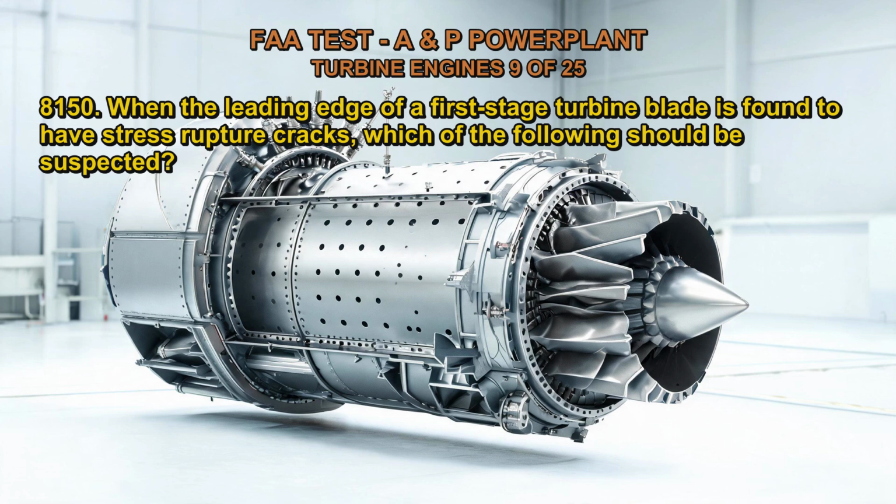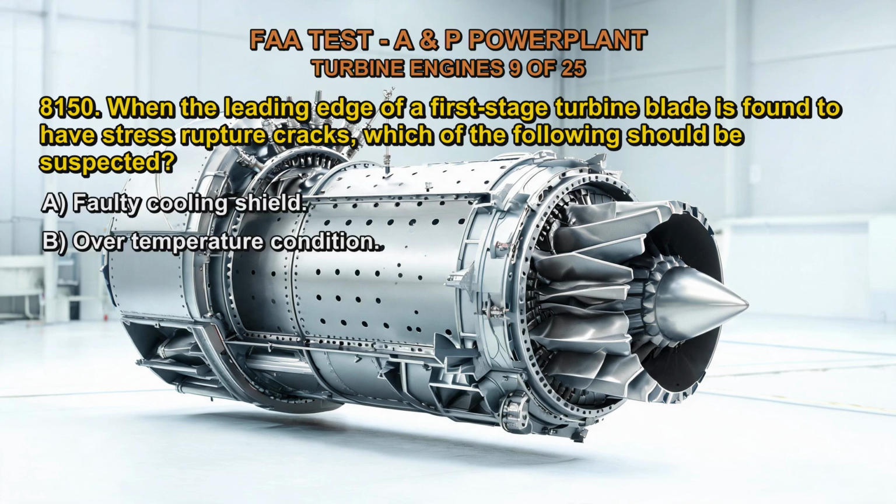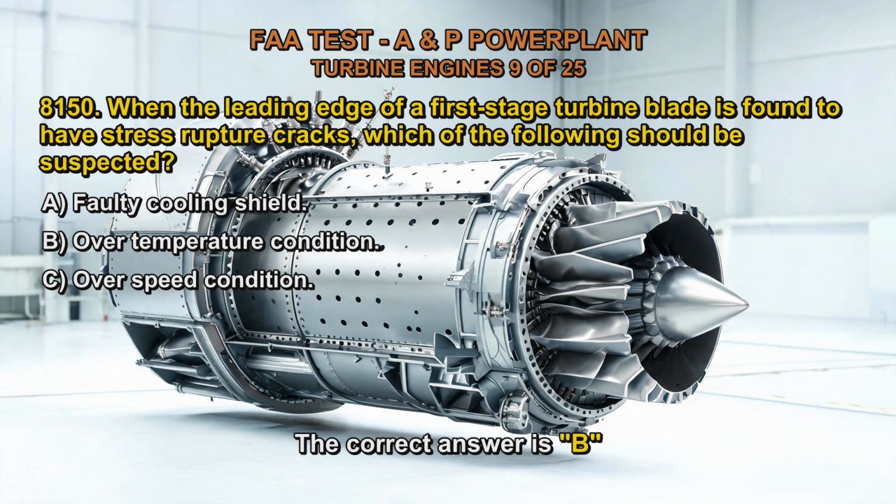8150. When the leading edge of a first-stage turbine blade is found to have stress rupture cracks, which of the following should be suspected? A. Faulty cooling shield. B. Over-temperature condition. C. Overspeed condition. The correct answer is B.